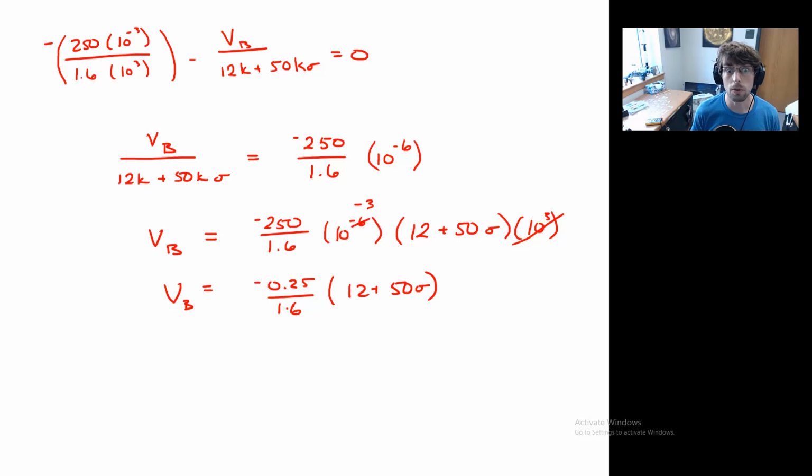Now we're told that the saturation of the amplifier is plus or minus 5 volts. That's the power supply. We're told that it's an ideal amplifier, so it's okay to use this power supply as the limit. Now in reality, as you're probably well aware, the saturation actually occurs slightly below whatever the powering limit is.